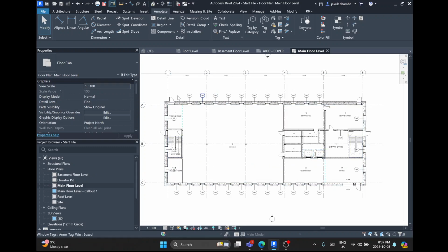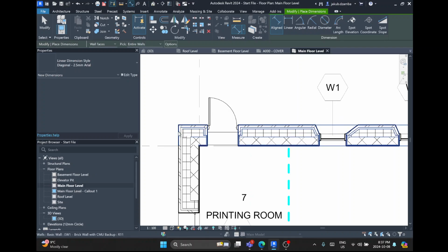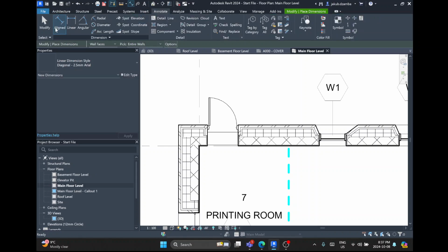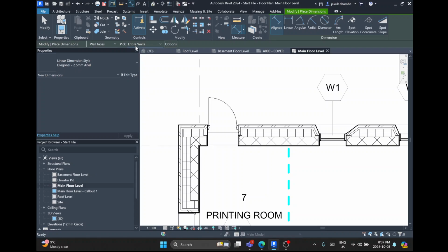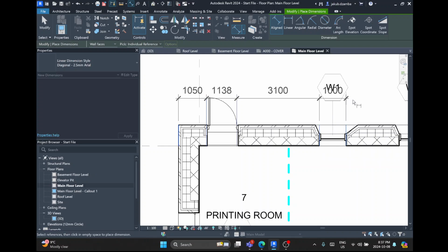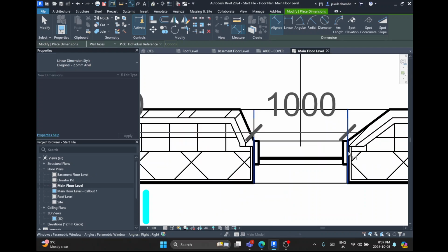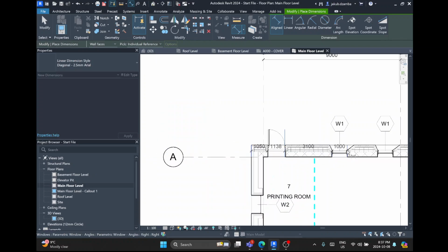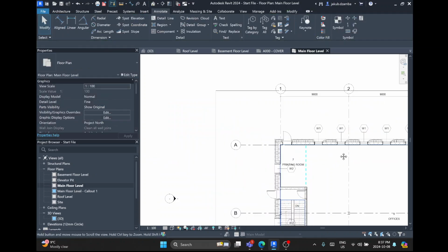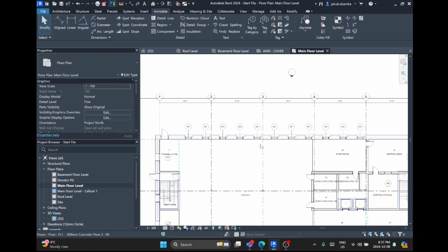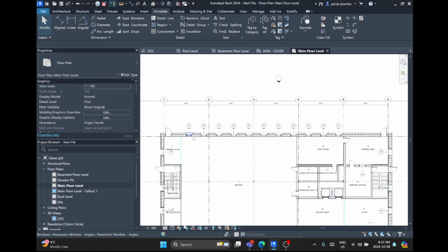Okay. Now dimensioning stuff. So let's say I want to dimension this wall. It's an exam situation. I'm running out of time, and now I'm like, oops, that's not what I wanted. Annotate, aligned. Usually this is automatically set to individual reference, and you just dimension one thing at a time. And now, maybe you're running out of time saying, oh geez, I gotta do this really quickly. And it can get frustrating. You're really zooming in to catch every line, to make sure it's the right line. So maybe in that situation, just slow down a bit and do something that'll actually get you further ahead.